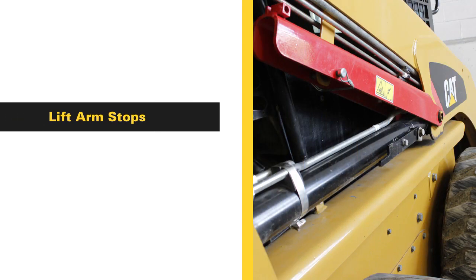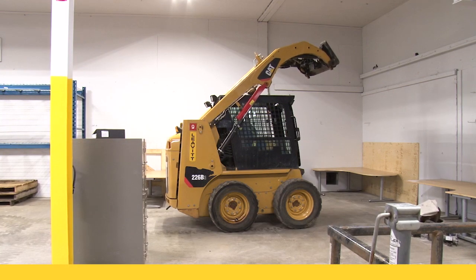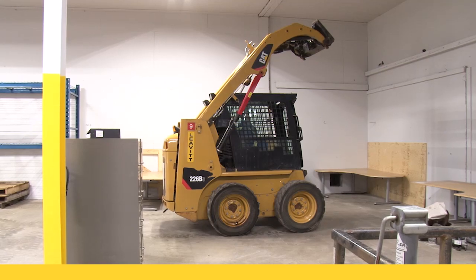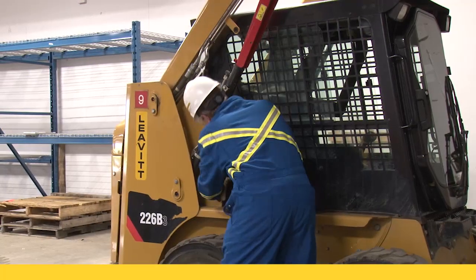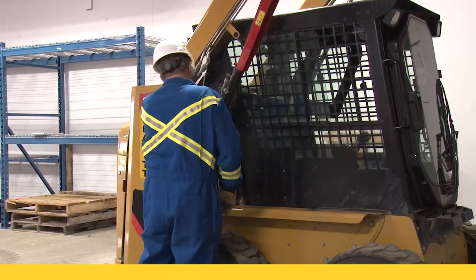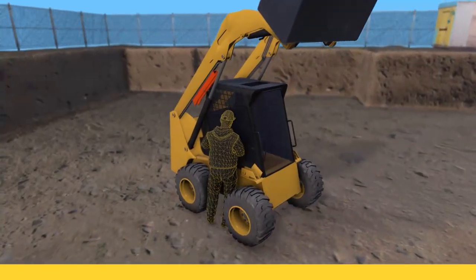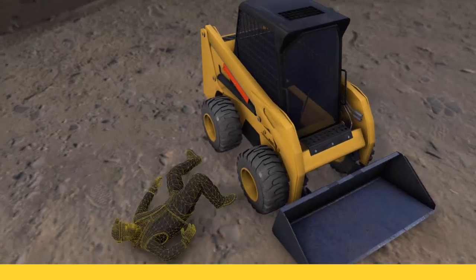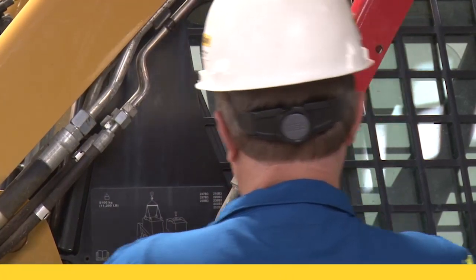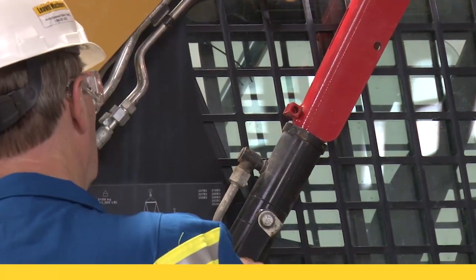Lift arm stops. Lift arm stops are safety devices that fit over the lift cylinder and prevent movement. The prevention of movement is particularly important when conducting maintenance because if the hydraulics fail while a mechanic is working under the arms, they will come down and fatally injure the mechanic. Therefore, you should never work on a machine that does not have stops or restraints in place.